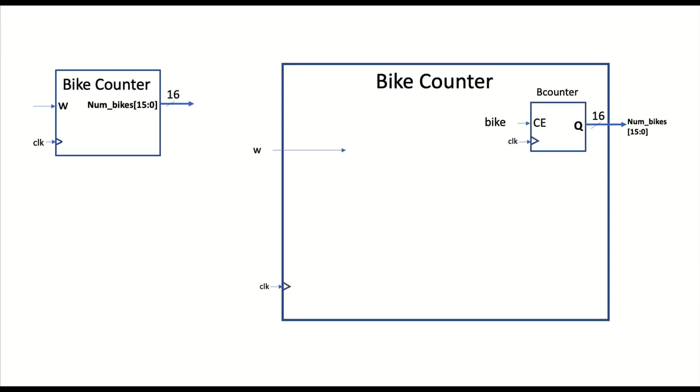Yeah, but how do I tell? An edge detector will tell me when the first wheel hit, right? And then afterwards, I need to know that the wheel went low again, and then I need to count, right? Yes? So, like a state machine hooked up to another counter? Another counter? Okay. Or kind of that counter serves as both an input and an output to the state machine?